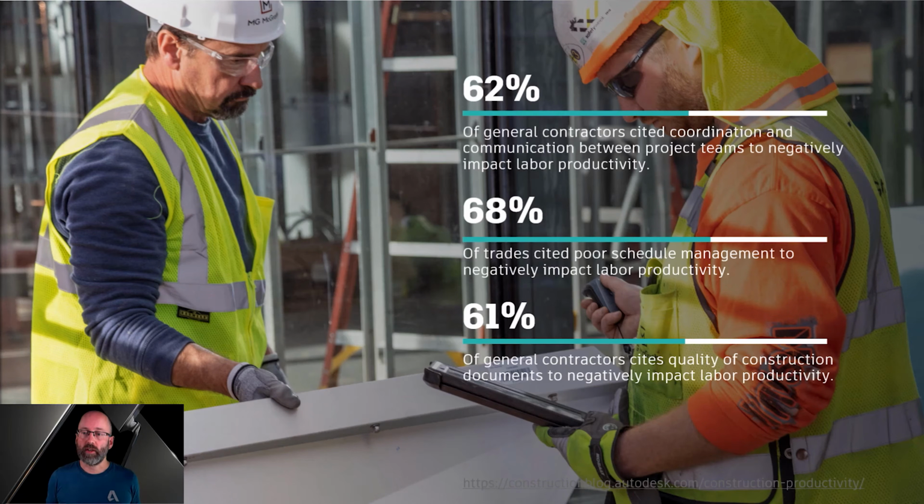So in this class, we're going to learn about new functionality released with Autodesk Inventor 2022 that allows us to export a native Revit project from Autodesk Inventor, and we'll recap on the functionality introduced with Inventor 2021 that allowed us to reference a Revit project file into Autodesk Inventor to use in coordinating our designs with the collaborative 3D design model, or BIM.